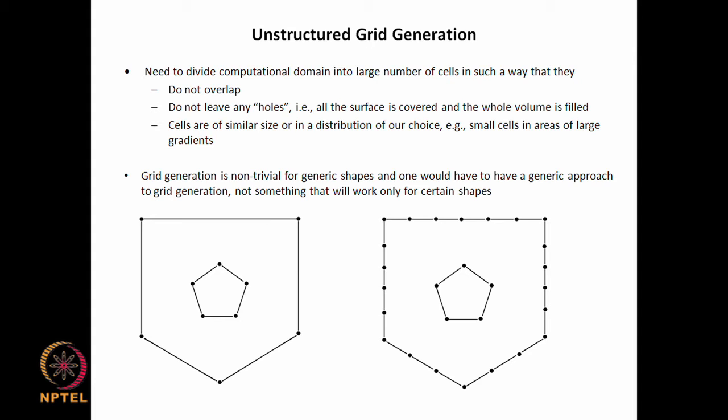So you should want to have a decent number of grid points. For example, if this is the flow domain shape and if I am expecting some profile here, then I would like to have maybe 10 points in between. Okay. So if I am looking at 10 points, based on that I can say that I would like to have a grid spacing of so much.